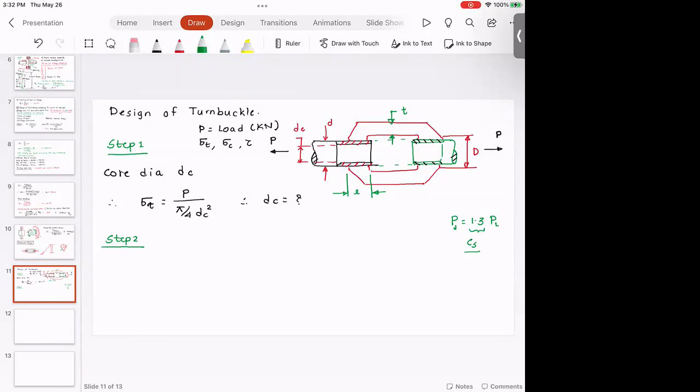There will be rain, there will be mud, there will be corrosion, there will be some other environmental effects. So you want to slightly over design to compensate for these unknown factors. That is why they use the service factor.